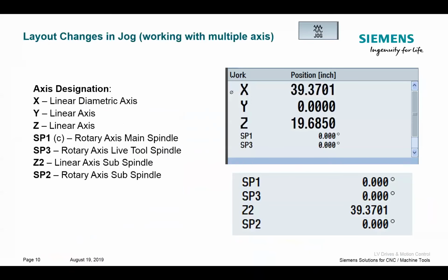It's always good to get your head around the kinematic setup of a machine, especially with machines that have a lot of spindles, because the commissioning from OEM to OEM is going to be different.